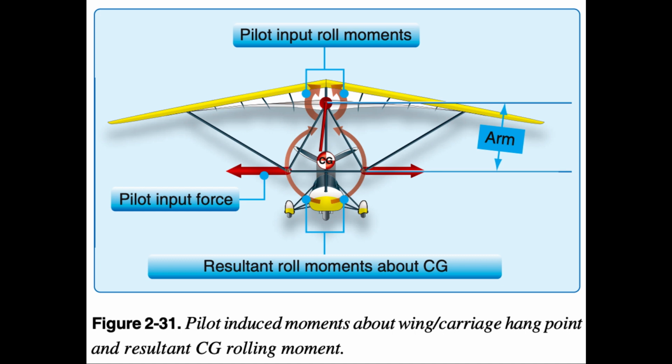Roll stability summary. Overall, roll stability and moments are a manufacturer/make/model balance between dihedral/anhedral, wing twist, nose angle, airfoil shape from root to tip, and leading edge stiffness. Some designs are stable, others neutral, and others can be designed to be slightly unstable for quick side-to-side rolling.